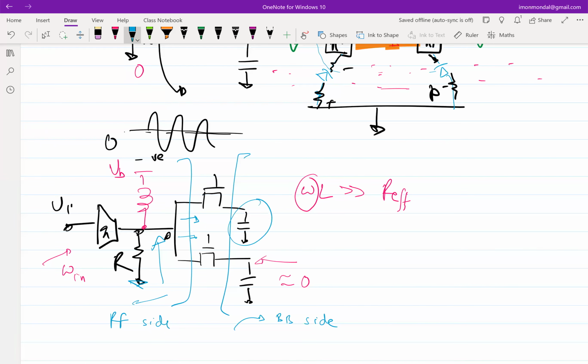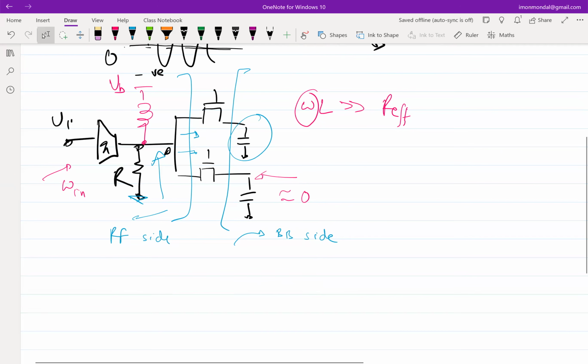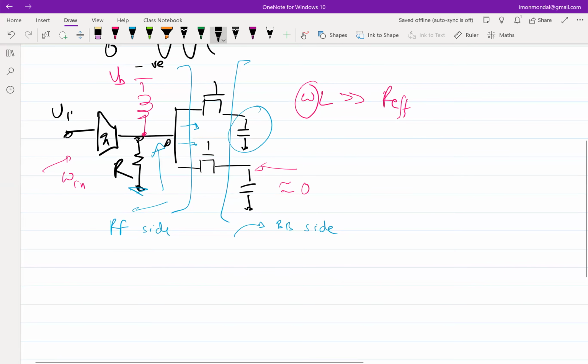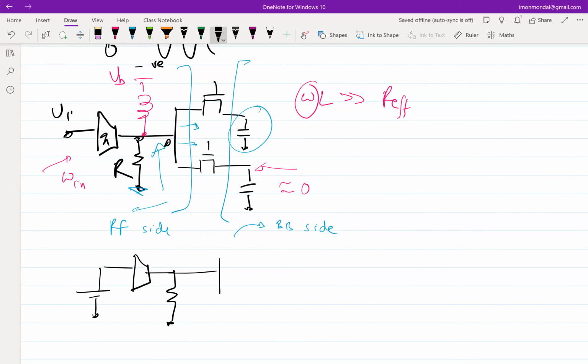Yeah, sure. But okay, do you see an issue with that? In this particular example, you can put, right? So his point is if I put a DC voltage here, so VDC, this current will be GM times VDC, and it is going to go into some effective resistance, and I can tweak the value of VDC to set the value.